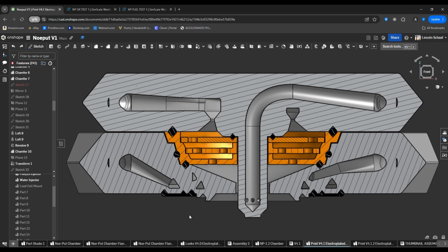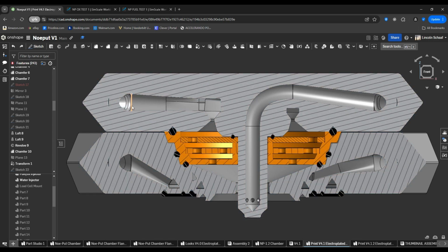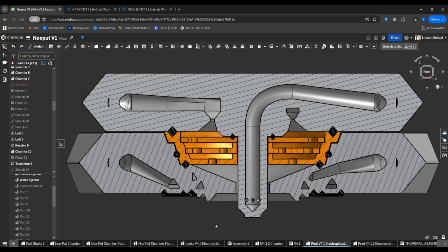So that's the propellant system as a whole. For a quick overview, on the left hand side we have the nitrous oxide enter, go through the catalyst bed here, decompose, and exit as a wall of gas surrounding the pintle. On the right hand side, the ethylene enters, goes through this channel, and exits through 7 holes in the pintle, colliding with that wall of nitrous oxide and combusting,